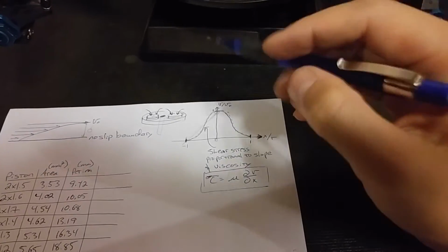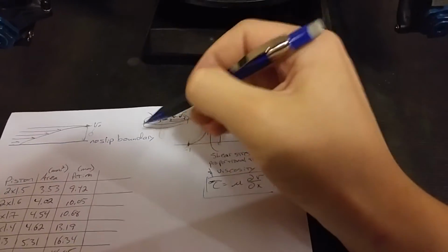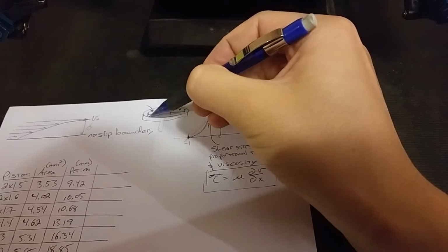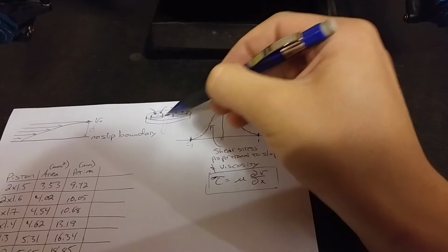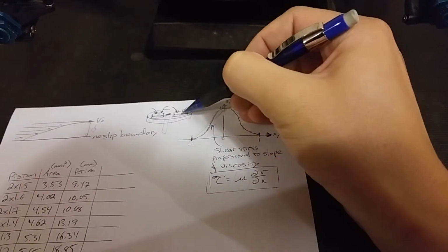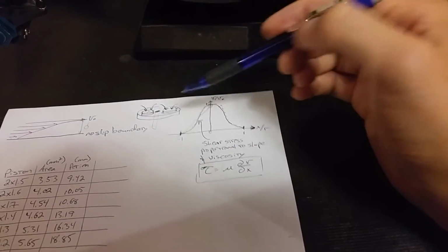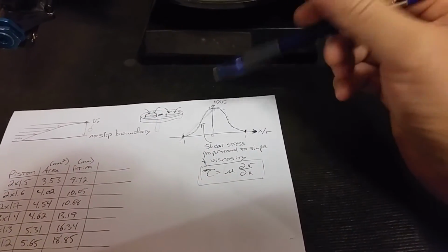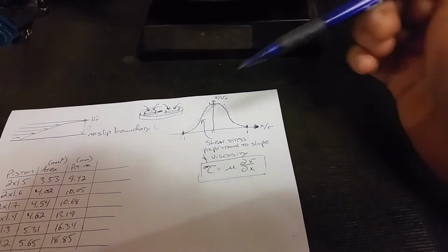Now, this effect is taking place around all of the open surfaces that you have, not only the top surface of the shock piston, but also the inside sidewall of the piston holes. So basically this shear stress effect is velocity dependent, and it results in what we call pack.